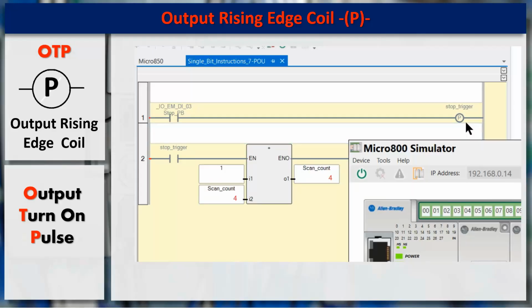But they're often used to make sure that something happens at the same time. So if you want to send a signal out to another PLC, you will pulse it and say, okay, I'm going to send this bit out and it's only going to get sent once. I don't want to keep filling my buffer up with too much information, etc.